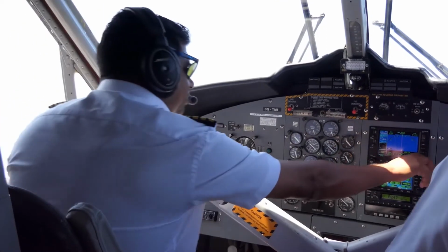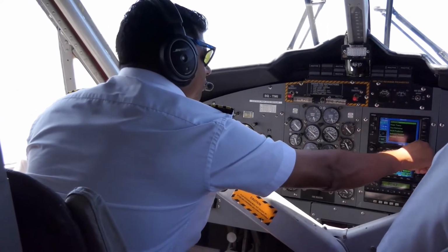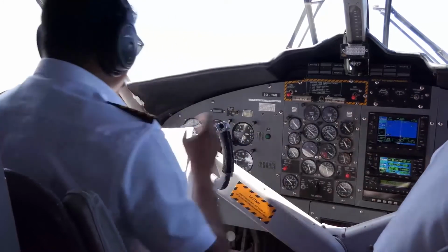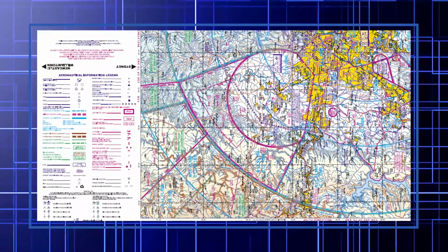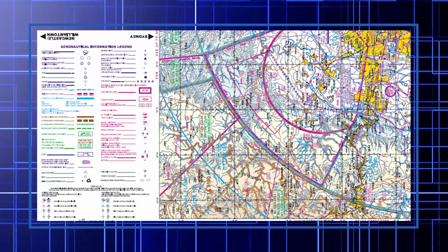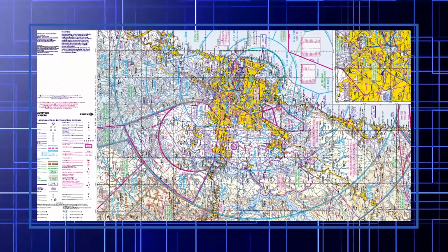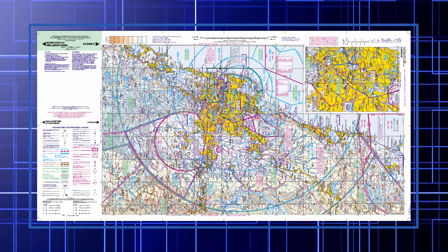and air service navigation providers. VTCs are designed for visual operations near terminal areas. They contain some topographical detail and appropriate airspace, radio communication, and navigation aid information. VTC would be a useful chart when planning for a drone activity. However, as you can see, VTC contains a lot of information that is at times difficult to decipher without training and study. So in this presentation, we have selected the airspace information most useful for illustrating drone flying regulations.